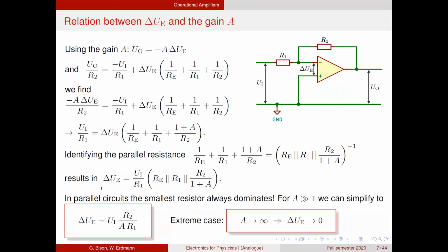Okay, let's have a look at the output impedance. As we've seen at the beginning of the lecture, output impedance is an important concept. So it basically means how strongly does the output voltage depend on the current that we draw out of the op-amp. So if we have a large resistor here, where the dotted line is everything inside our op-amp package, then the output voltage would depend on how much current we draw out of it, because there would be a voltage drop over this.